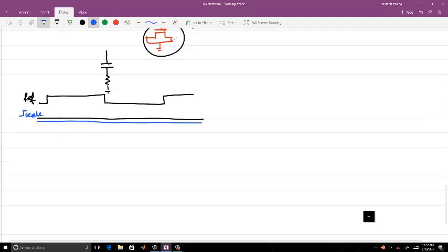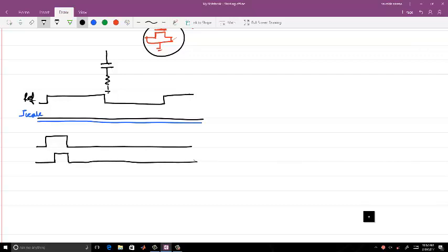Adjust the up down timing. So what should be the up pulse? We are right now considering only the leakage. So the up pulse will be something here, and I plot the down pulse as a negative thing. Assume that there is no mismatch between I up and I down right now.